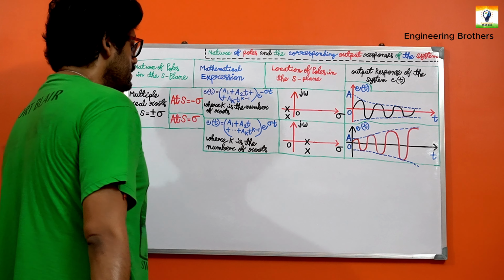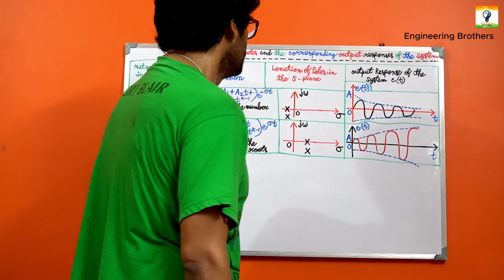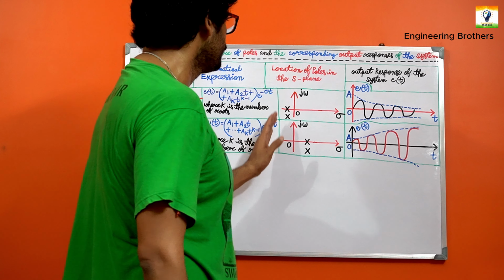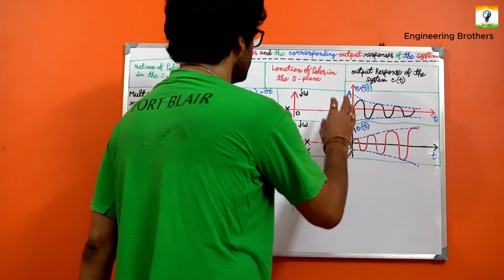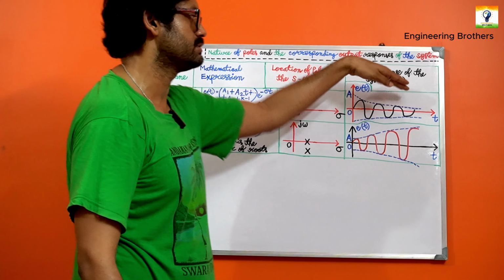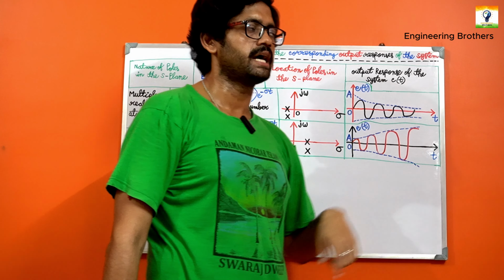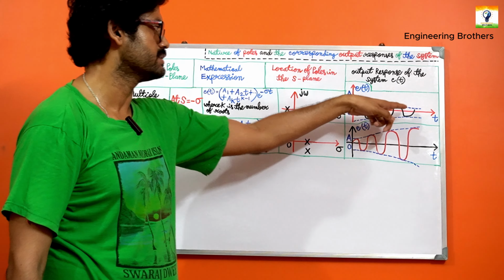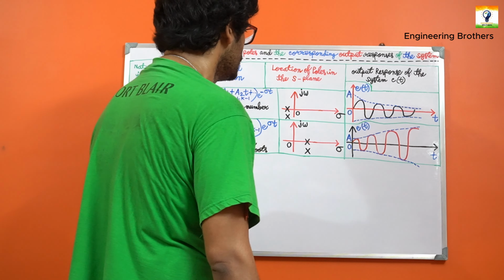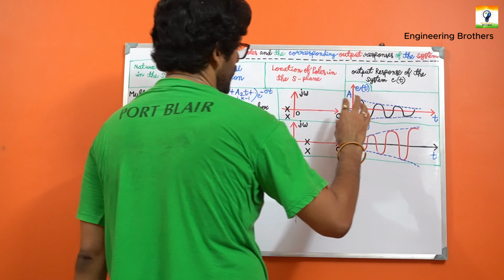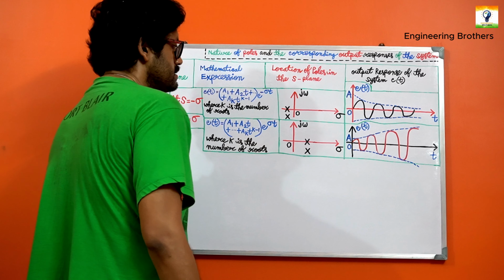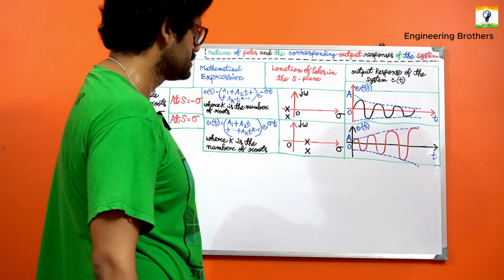Though I want to say another thing here. As you can see that the poles are placed at the left hand side of our given s plane, we can say that this is going to be a stable system. And this is another analogy: as you can see that the c(t) curve is going towards zero, that is another analogy to say that the system is stable.